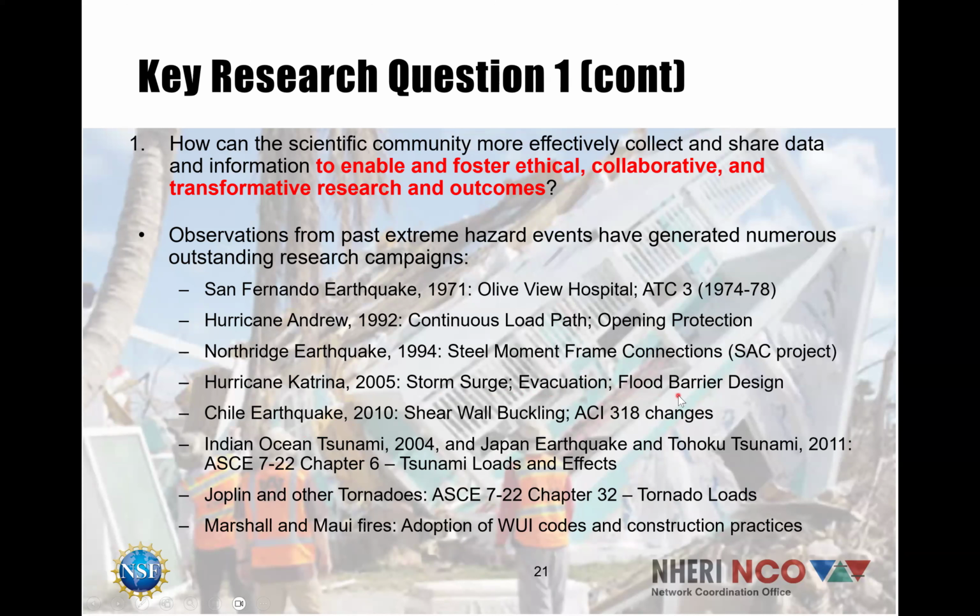Chile, a flood barrier design, the barriers around New Orleans, obviously not adequate. They were high enough, some water might have gone over the top, but you'll never fill up those neighborhoods with just water going over the top of the barrier. The problem was the barriers failed because that water going over the top scoured the foundations. The foundations were not anticipating overtopping. And once the barrier fails, then the entire below sea level area will fill with water. And that was the biggest problem in New Orleans.